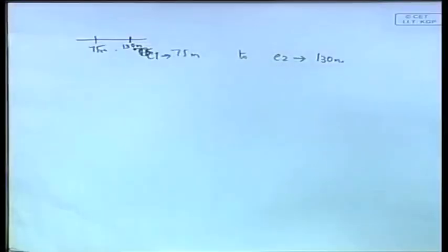So here we are adding 600 tons. No, it's not like that. It's actually told to distribute 600 tons. Means some of that weight is added at 75 meters and some of that weight is added at 130 meters. The center of mass of that 600 tons should be 15.31 from the center of flotation. Yes, that is what they have done.